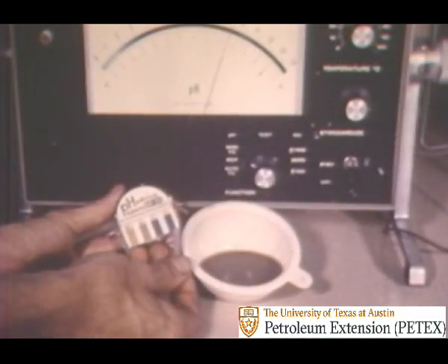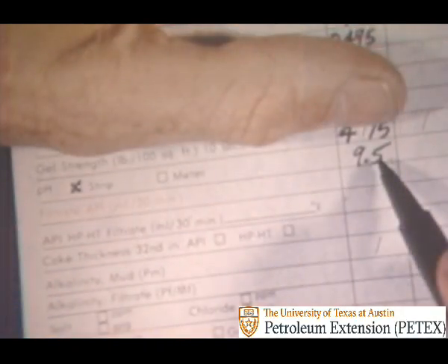By using hydrion paper, litmus paper, or a pH meter, the next thing the mudman determines is how acid or how alkaline the mud is in terms of pH. Almost all mud should be alkaline. That is, the pH reading should be above 7 in order to minimize drill pipe corrosion and maintain the mud stability. This mud's pH is 9.5.